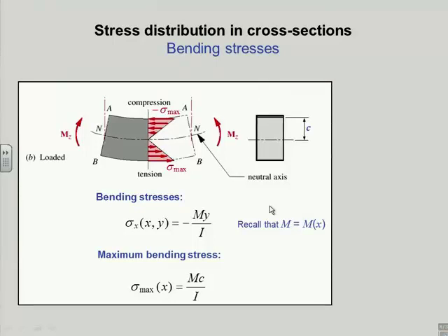And it is positive, or tensile, which we call positive, below it in this case. I'm upside down. The tension's on the bottom here, and the compression's on the top. And I've turned the arrowheads around. You often will see that drawn as a straight line right across with the arrowheads for the compression on the left-hand side of the center line. That's a perfectly good way to express it.